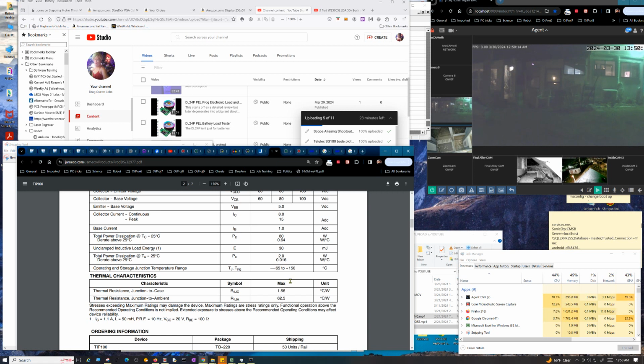But that's just one very brief example of where your power buildup may be coming from inside of a transistor. And that assumes all things are equal and the thing doesn't thermally run away, which it still can do even as a switch, if you're not careful. Because all transistors can thermally run away, if you don't have something that keeps it in check, like some kind of resistor in series with it, for example a power resistor, like we were talking about earlier.